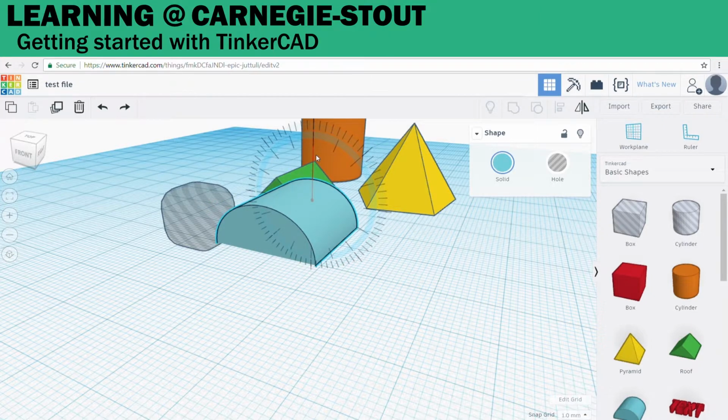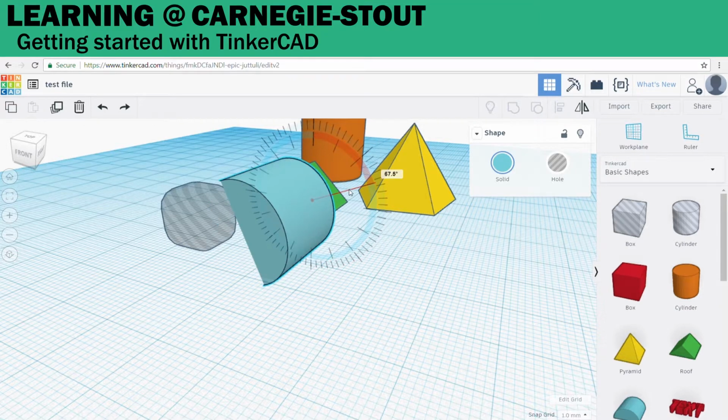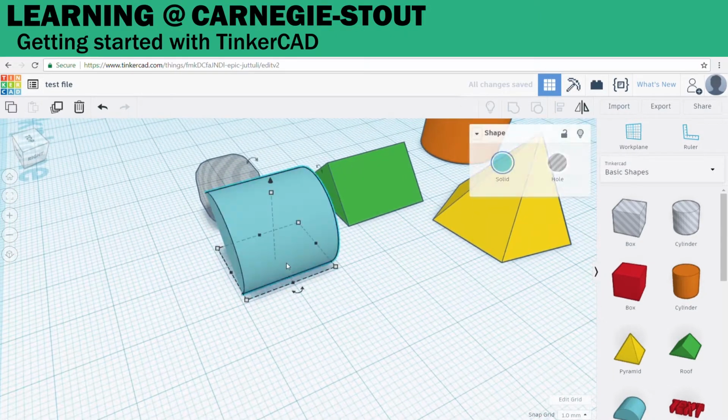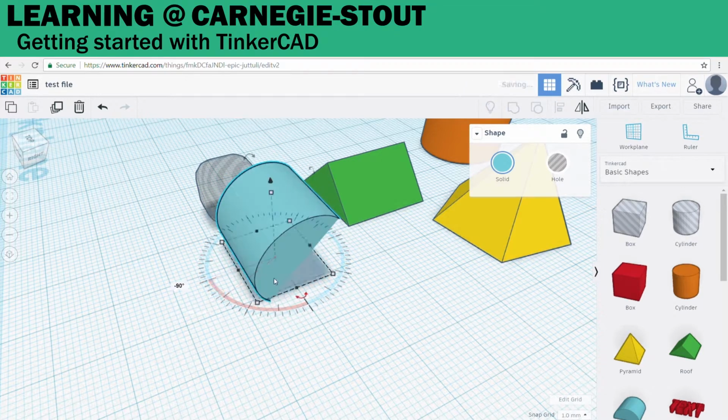If, while you are dragging your mouse, you have it inside of the circle, your shape will snap to 15-degree increments. If you move your mouse outside the circle, you can move 1 degree at a time. You can also change multiple angles at once.